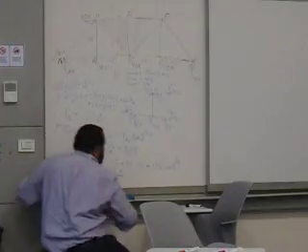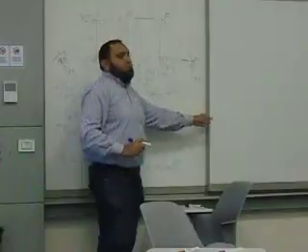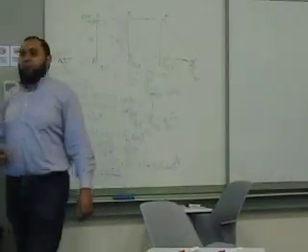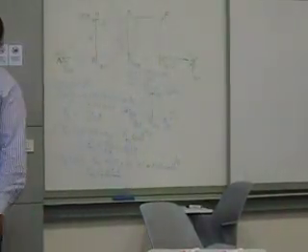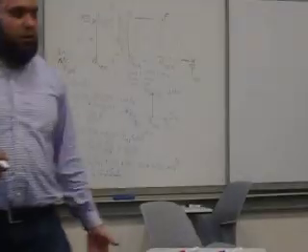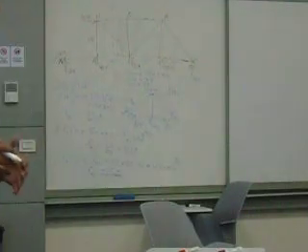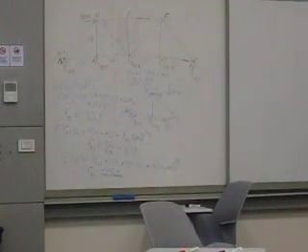That's a compression. Again, we are always assuming that tension is positive and compression is negative. And it is very important not to make a mistake in something like that. Why? Because, inshallah, when you go to the design course, you will know that designing a tension member is totally different than a compression member, especially in steel, or any metallic structure. Because in compression, they can buckle. So the design criteria is totally different. We're designing for two different things.